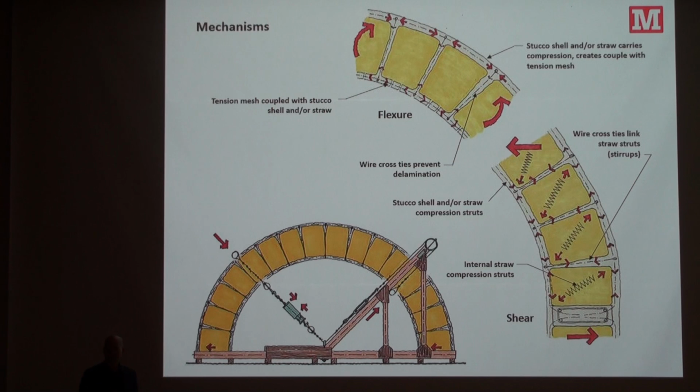And then from there, we came up with a full-scale test where we made a full-scale 4-foot slice of the wall. And I came up with this loading apparatus where there's a hydraulic jack in here, and you pull from the saddle, and it goes around the pulley, and you pull out from the saddle. And that emulates seismic loads during an earthquake.